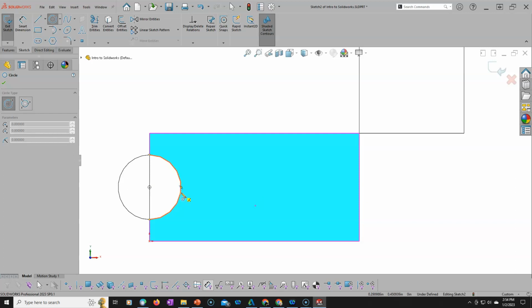And there's nothing really here to pick, but the arcs. I can look for the quadrants showing up as the little diamonds, the midpoint, the center, the midpoint. If I just go to the quadrants again, we can infer. If I kind of hover over these, I can see the midpoint. I can see an endpoint. Let's see if we can pick up a midpoint. Yeah, really not dragging, but there's one to that point.